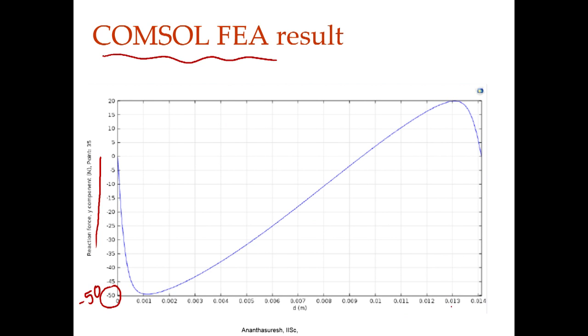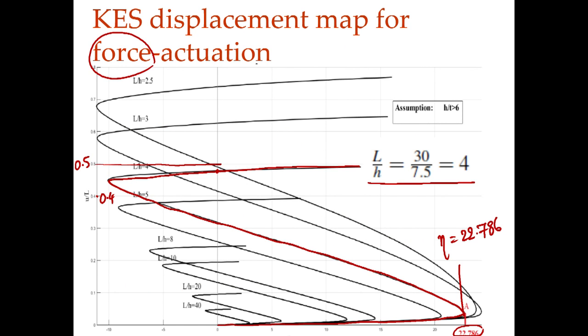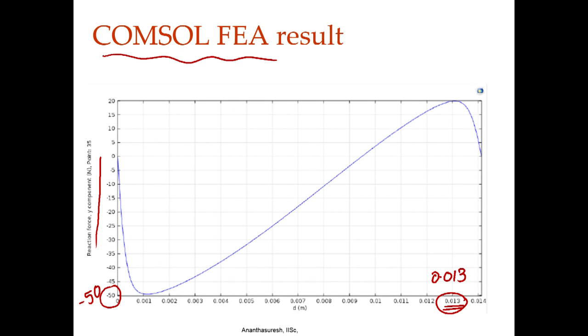It actually comes there with the travel which is indicated over here. We said 13 millimeters, this is 0.013, that is exactly what we have, because kinetoelastic maps are created using finite element analysis. It is no surprise that we get back what we have. Those maps contain the information of a lot of finite element analysis, even though to create that map you only need a handful of analyses. For example, to create a map like this, if there are 1, 2, 3, 4, 5, 6, 7, 8 curves to draw, you need only one finite element analysis for each. If you do that, you have this information so that you can design a number of things after that, for stiffness, force-deflection behavior, strength, and so forth.